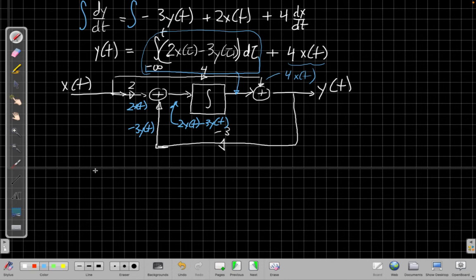The main change is that instead of writing things in terms of delays, you'd think we'll just use derivatives because we're doing differential equations. In theory, you could make those and draw those diagrams, but they're not practically the way we want to build systems down the road. We want to build them with integrators because they're electrically more stable.